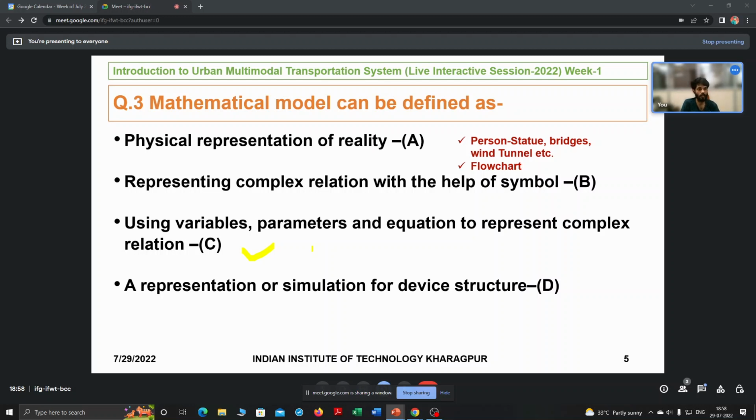Your x1 and x2 are distinct variables. They are independent. There is no relation between the characteristics of a vehicle and the characteristics of a road, right? So those are independent variables, x1 and x2, and y is a dependent variable. So your speed is depending on those factors. So now you can model it.